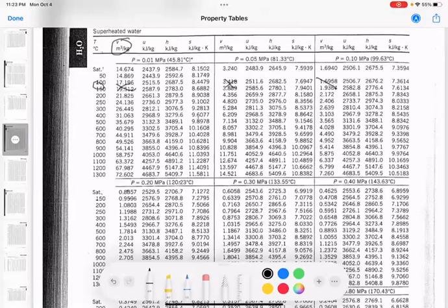Okay, and we do the exact same thing here, but you'll notice, of course, the temperature we want is a bit lower. So instead of interpolate, we actually have to extrapolate here to a lower temperature. And once we do that, we get our next specific volume. And then with those two, one interpolated, one extrapolated specific volume, we have to relate that to the pressures 0.2 and 0.3 and see how far in between we are. And what you'll find is that we're just slightly above this 0.2. We're at 0.21 megapascals of pressure.